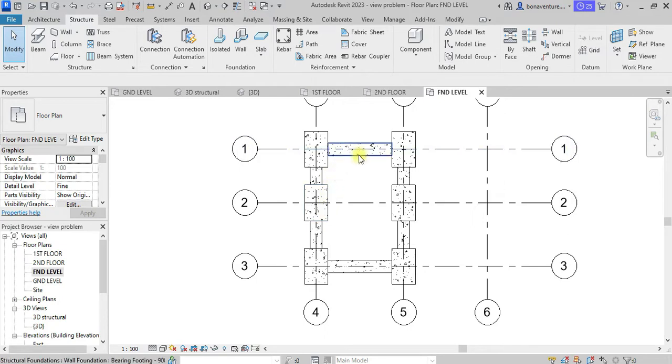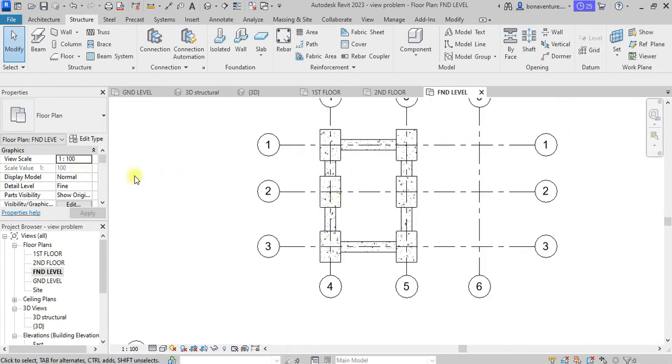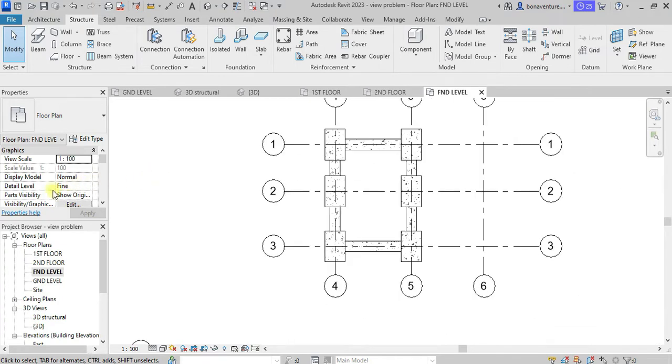This is just how I'm going to print out. Assuming I want to print out a foundation drawing, but I want all these lines to be continuous, not having them separate and joining together at this particular intersection, then what do I do? That brings us to this particular problem, which is under detail level. For you to have a foundation that is joined together, the outline joined, what you need to do is to come under this detail level and click on make it coarse.